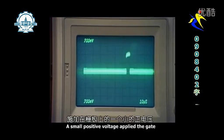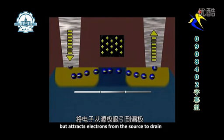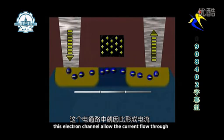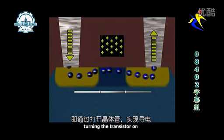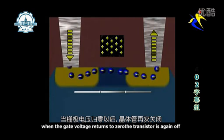A small positive voltage applied to the gate repels the positive charges in the P-type substrate beneath the gate, but attracts electrons from the source and drain. This electron channel allows current to flow through, turning the transistor on. When the gate voltage returns to zero, the transistor is again off.